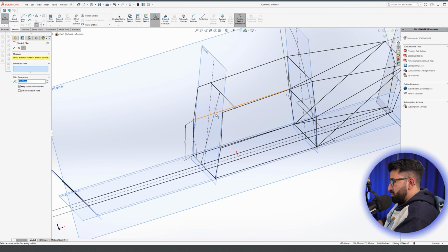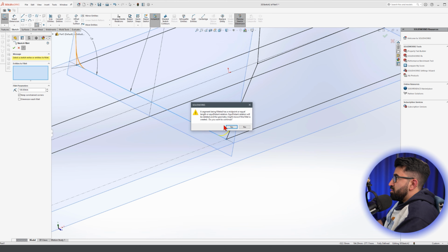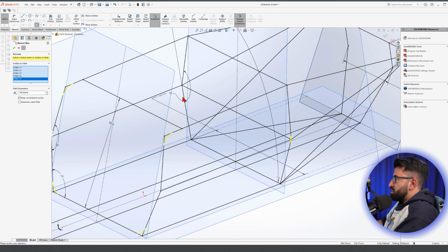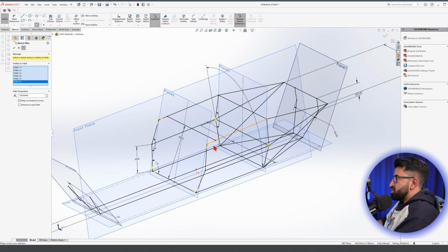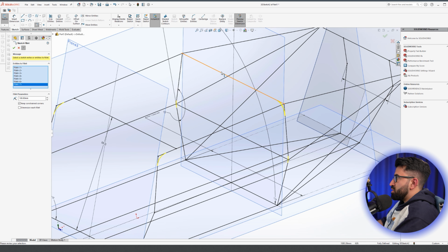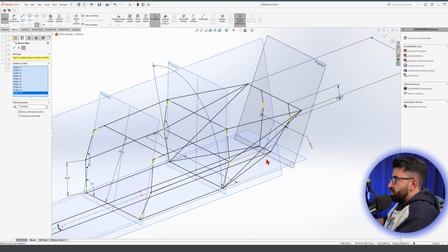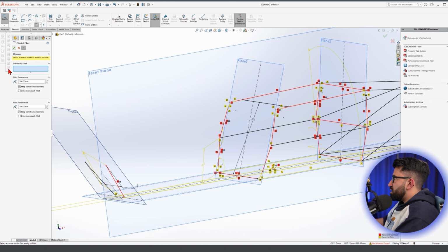Now I can even round the edges like this. Yeah, no problem. Let's round this one and this one too. But when you round, you create misconnection or disconnect. But it's fine. We will fix this as much as we can later on when we are adding the structural members, that is the profiles of the weldments. In this case, a pipe. We can fix it right there. All right. I think at this point, you got the concept. So I will try to just wrap this up quickly.